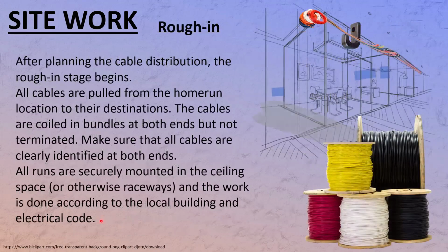Now, as far as cables, sometimes the cables come in boxes, and sometimes cables come on reels. So usually it takes more than one person to do the wiring. A bigger project would involve 3 or 4 people. For a small project, 2 people is good. Try to avoid a one-person wire pulling team, because